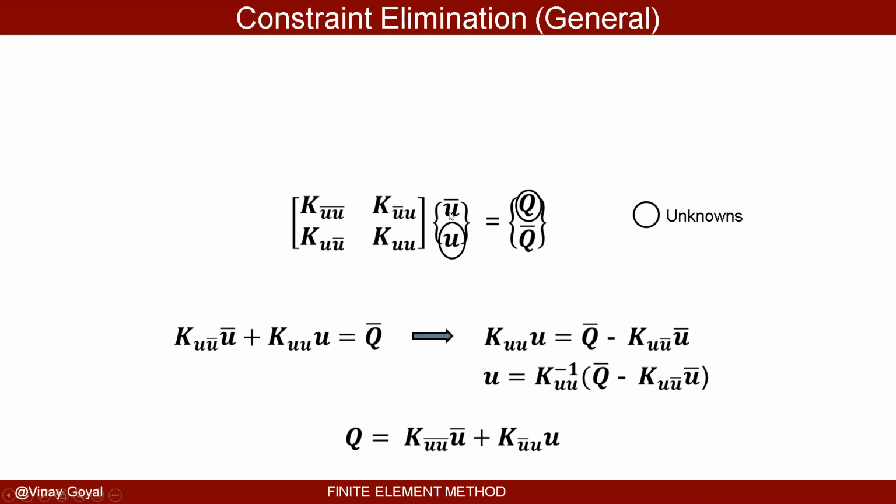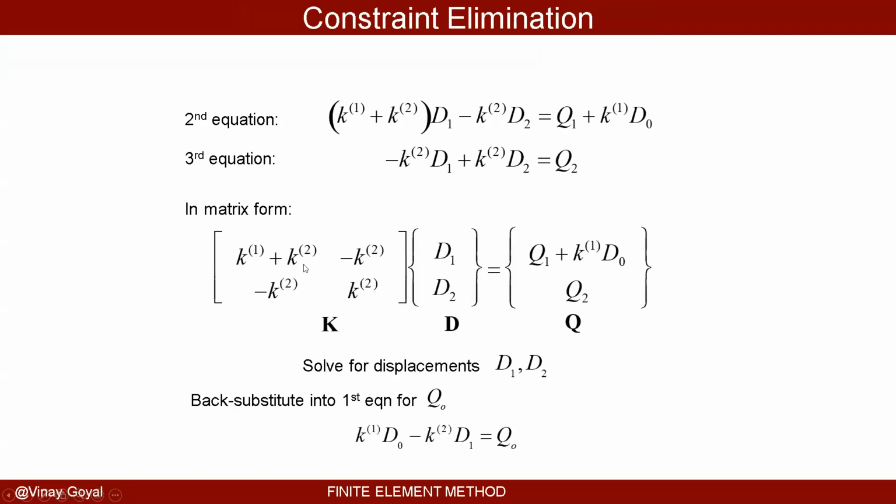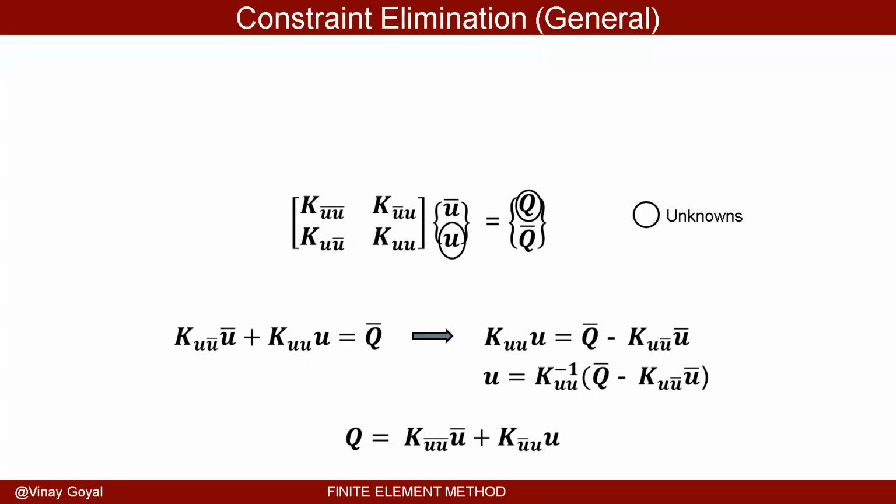This column vector is going to have millions of degrees of freedom. We divided that vector into specified values and unknowns. So these ones are known again. This whole stiffness matrix is known, just like the previous one. These stiffnesses you will know; these are values from the idealization process. The forces are known. And so we had to figure out a way of turning this into something that's useful. If we multiply the second row times the first column, I get this.